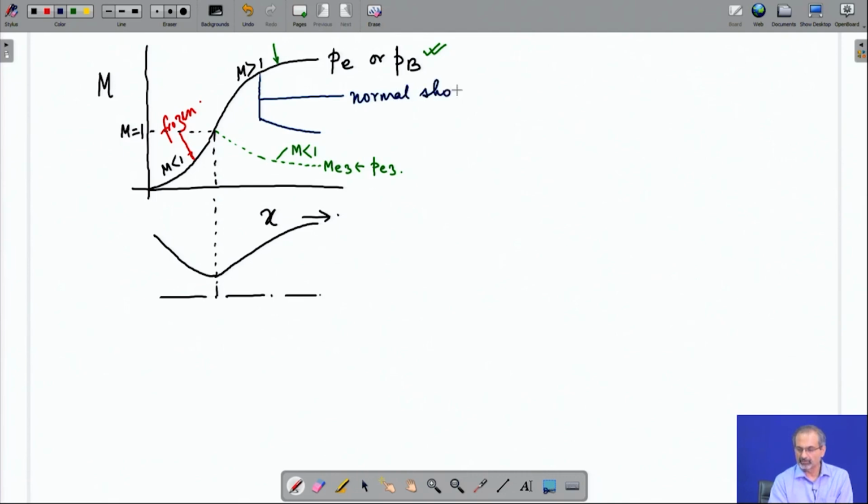A normal shock may be formed in the diverging part of the nozzle, here in the nozzle, and the moment it happens, you have a subsonic flow and you are giving it an increasing area, and therefore, it will slow down further, and that is how the Mach number keeps decreasing till it reaches the exit, if you are increasing the area. So, going by the geometric feature, that is how it is going to happen.